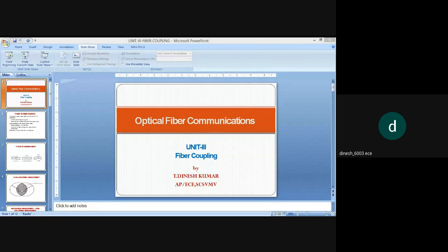So if all the modes of the optical beam fill the entire numerical aperture, as shown in the case of the equilibrium state, only that would be passed on. So in the second fiber, there will be only the equilibrium numerical aperture at the central region to pass on the power which is coming from the first fiber.